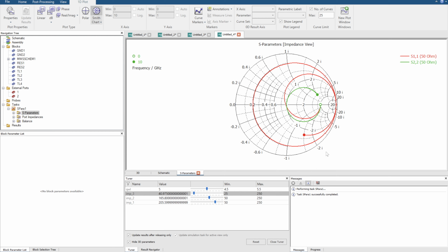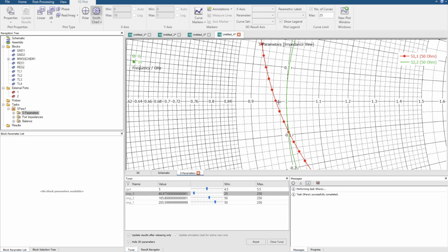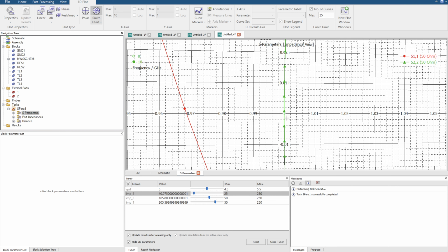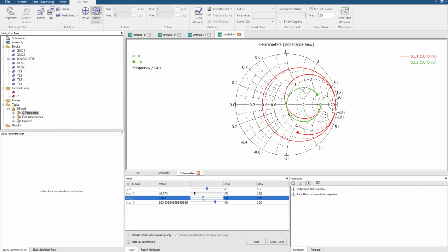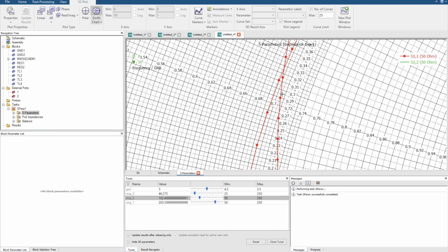So this is the benefit of using the Smith chart. As long as one of the lines goes through this normalized impedance of 1, then you've actually got an impedance match. So you can start playing with all the values here. Oh, that's too much. Let's start seeing how the middle one impacts it. Oh, so we're seeing how we've got this interception point here.